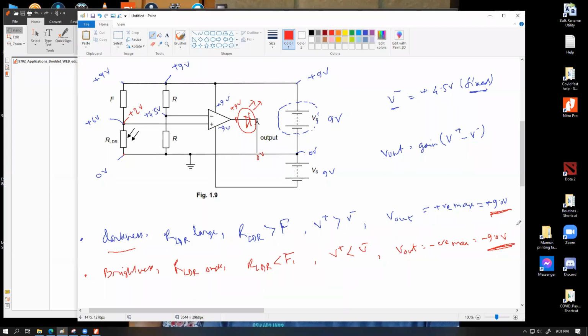There is another part for the second information, that is, we can fine tune this circuit, exactly at what illumination level, or if you say thermistor, exactly at what temperature this light starts to glow. I mean, up to which level of light this street lamp is not glowing, and up to exactly at what darkness this street lamp is actually going to start to give us light. You can fine tune this if we make this fixed resistor into a manually operated rheostat.